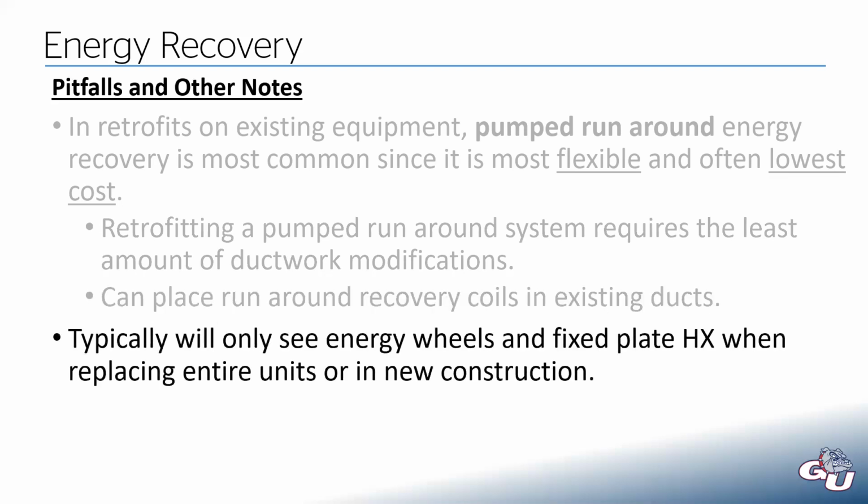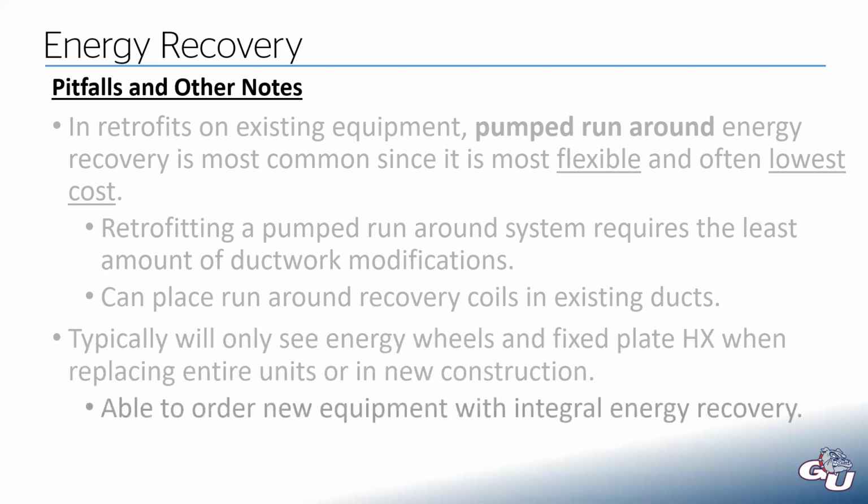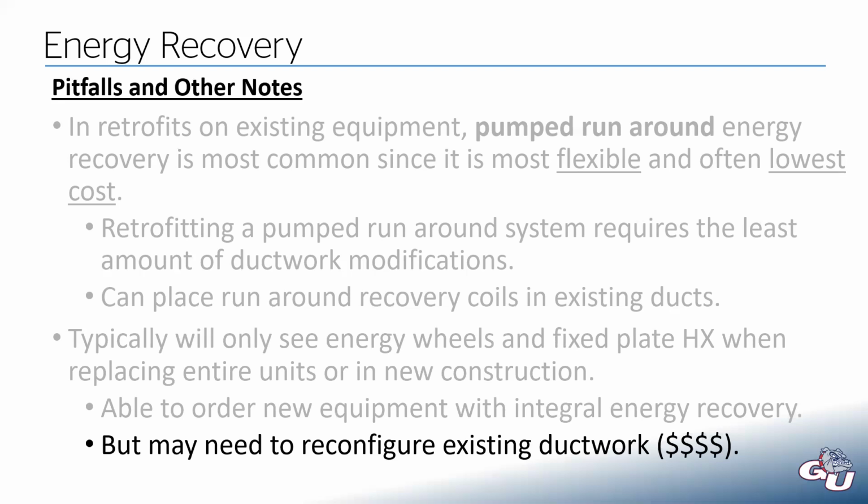Typically, we're only going to see energy wheels and fixed plate heat exchangers when we're replacing entire units or if we're doing new construction. Or I guess if we were doing a significant renovation where we're replacing the entire HVAC system, that would be a case where you would see energy wheels and fixed plate heat exchangers, because we're able to order the new equipment with our recovery integral to the units, but you might have to reconfigure the existing ductwork to make this work. And that could be very expensive.